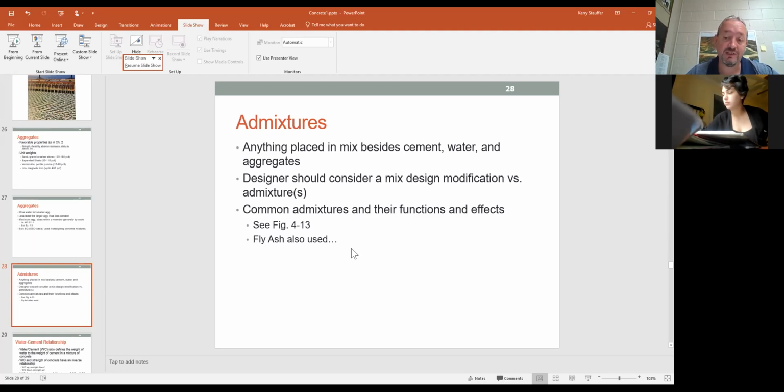Well, maybe they need to finish the concrete faster. So in order for them to be able to actually place a load, depending on what kind of finish they have, they might put some accelerator in there. And then I'm going to skip way down to decelerator, or retarder.